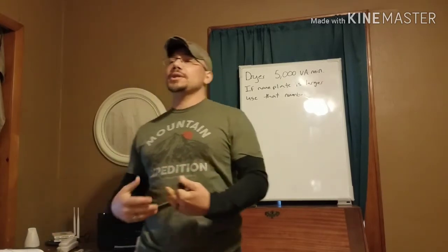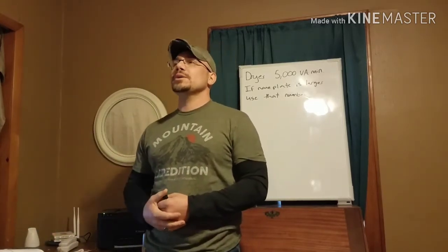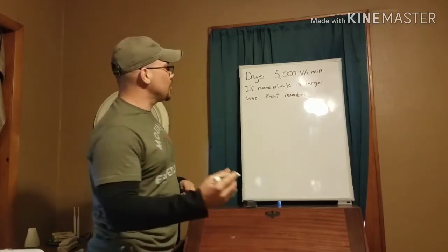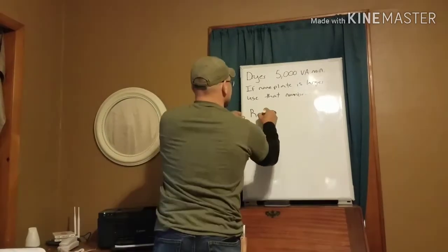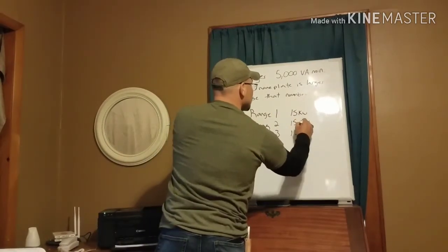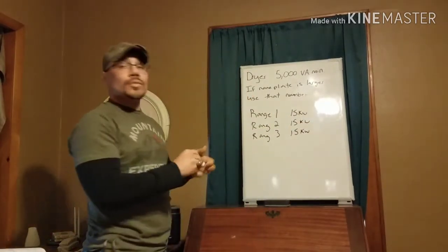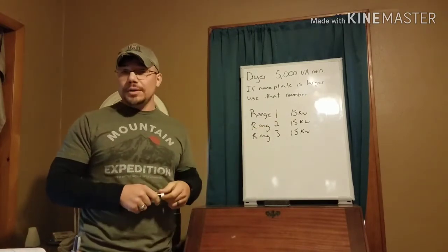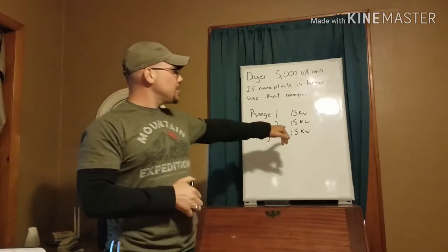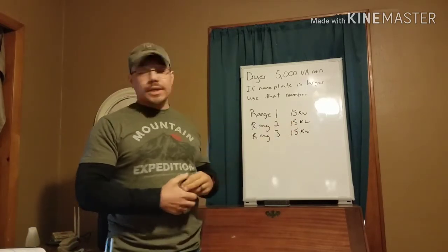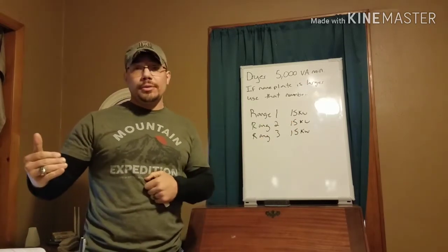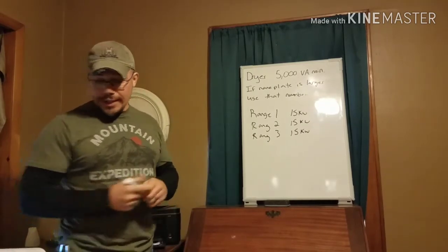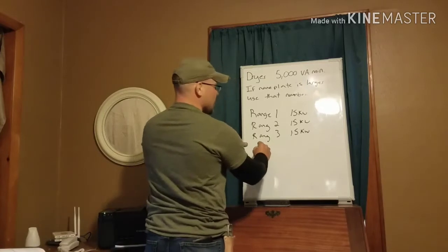So let's say we have 3 ranges: range 1, range 2, range 3, all at 15 kilowatt. Since they're all the same, we take our 12 kilowatt rating, according to that note, and subtract that out.